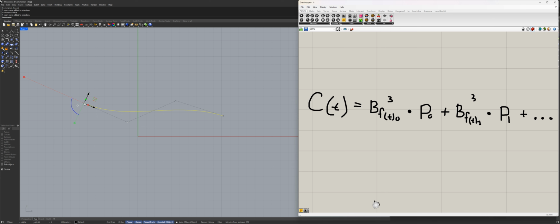On the curve, this point at the beginning basically shouts, come to me, pull the curve to me, I'm in control. And when this one is really active and loud, the further away you go through the other control points, the fainter its voice will be, and the louder the voice of the other control vertices. Like for example here, this control vertex is at full effect. It has maximum control.